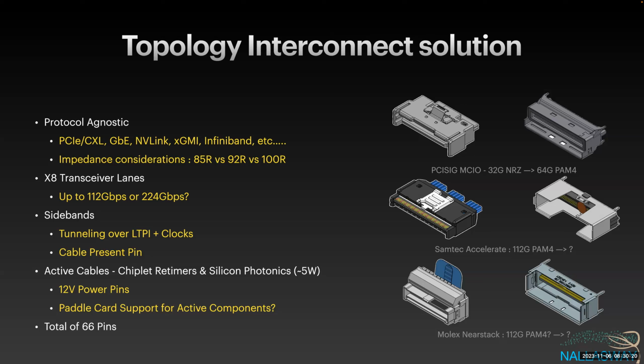And of the 3 connectors on the right, natively only MCIO supports a paddle card approach, mainly because both Samtec's Accelerate and Molex's NearStack have gone to wire straight to pin. They actually solder the twinax wire straight onto the pin for a good SI path. And so I'm wondering if we can do both of these, and I have some ideas in cartoon PowerPoint form, and that's where I'm thinking we need to innovate on the connector design here, so that we can get down to one connector that serves all purposes. The total number of pins based on that is about 66 pins.